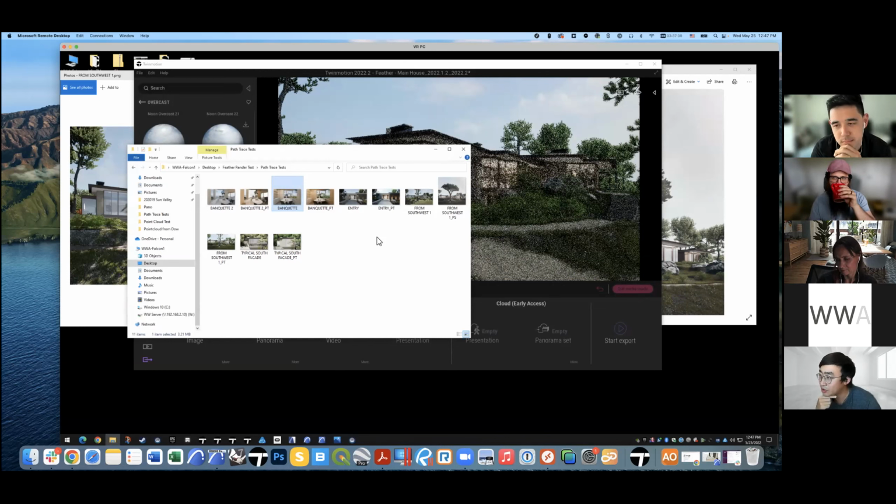There isn't too much time you need to commit to this kind of path tracing, because you're going to set up the lighting for the general lighting, like the interior lights and exterior lights, anyway. You just need to toggle the sky dome lighting and tweak the exposure intensity a little bit, and then I think you should be good to go.